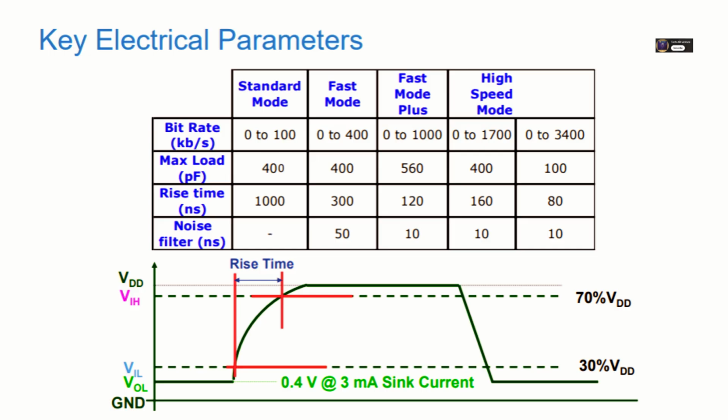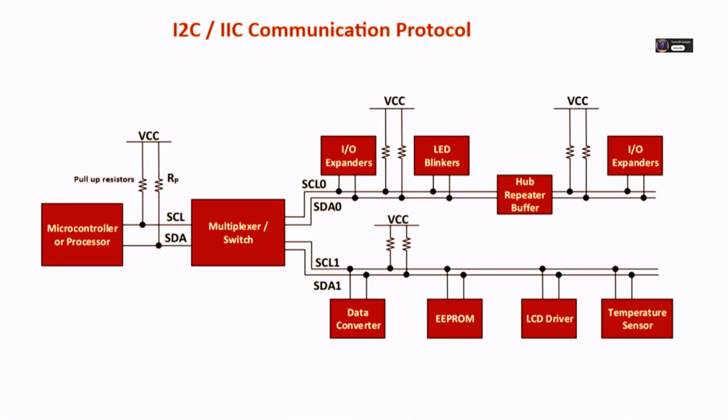And the other way, too strong, like a really low resistance pull-up, pulling really hard. If they're too strong, too low resistance, first, they draw more current all the time the line is low. This wastes power, which is bad for battery devices. More critically, it can make it too difficult for the devices to actually pull the line low. Remember, they have limited current sinking capability.